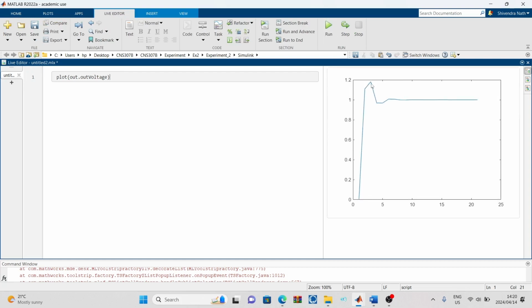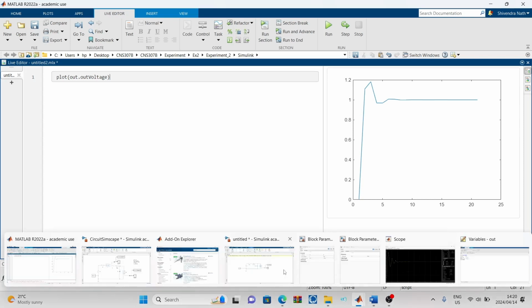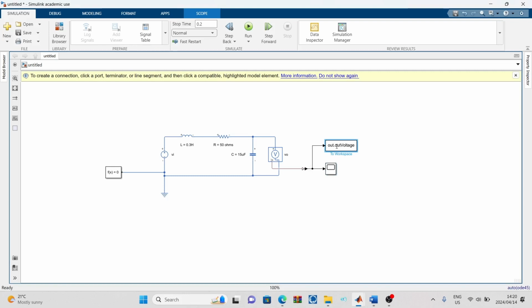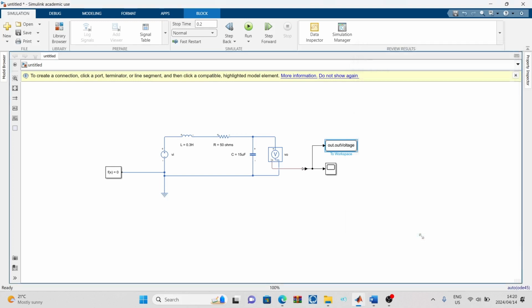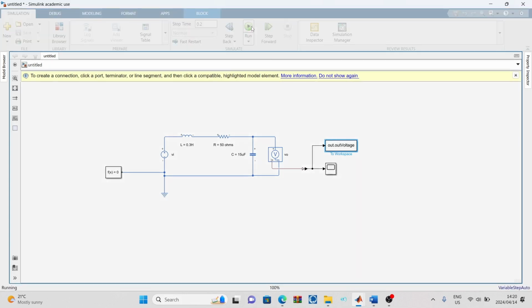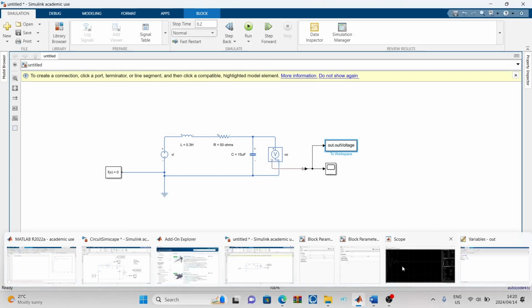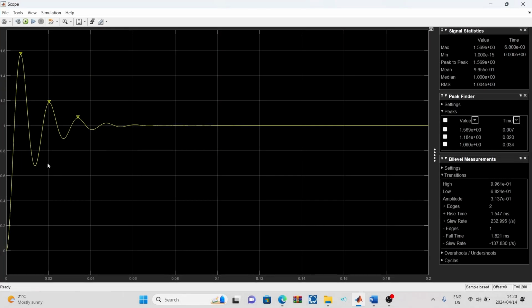Then as you can see, it does give you a graph something like this. And we have this sharp punch due to the sampling rate we have, which we can change here. We can make our sampling rate higher, let's say 0.001. Then if we apply and let's run it again, then you see it's smoother now because we have more data points.